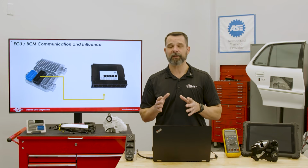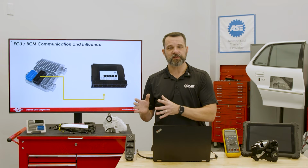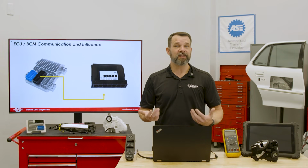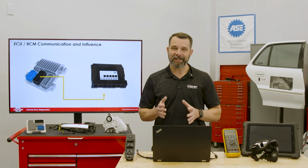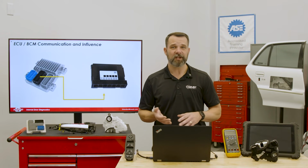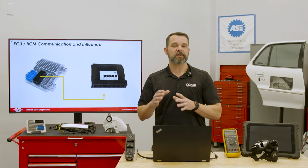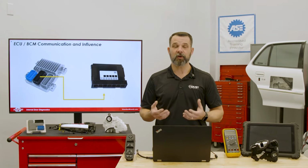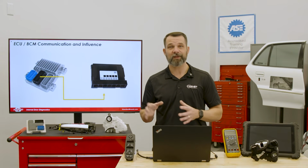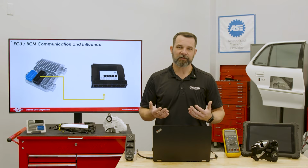And then a big one here, this is a big cause for misdiagnosis as well, is the charging system and the voltage state. If the ECU detects low voltage, it can signal the BCM to disable things like the auto up-down function of the windows, power sliding doors, and even the power liftgate, purely to protect the battery from dying. So, going into any diagnosis within these systems, you should always include a charging system and a battery test.